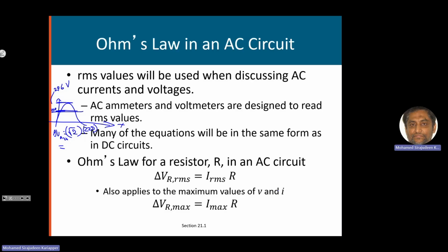296? No. 311, I don't know. Okay, are you sure? All right, 311. I didn't check. Somebody told me in the last class, okay? Right, anyway, my point is, this 220 volt is an average value. So actually, the voltage is varying between 0 and 311. So it goes from 0 to 311, comes down, reverses direction, and so on. So it's a sinusoidal waveform.